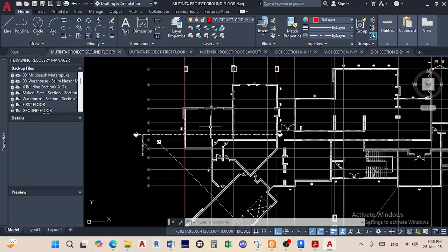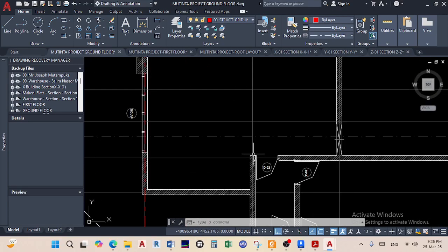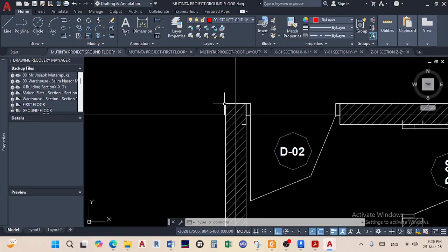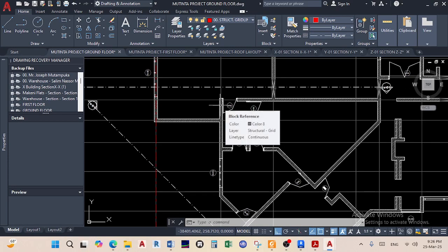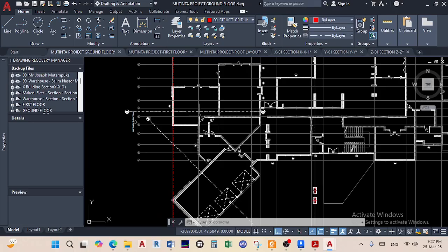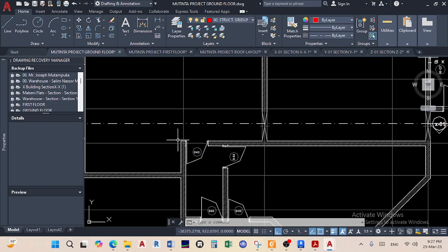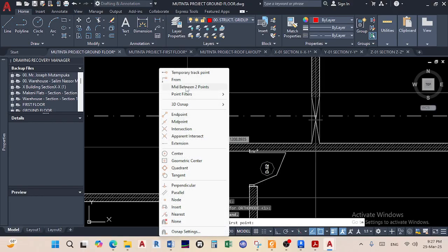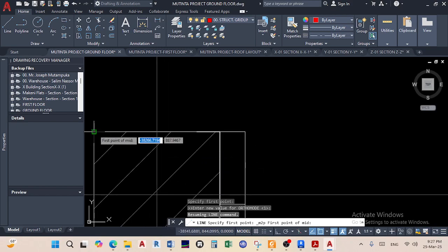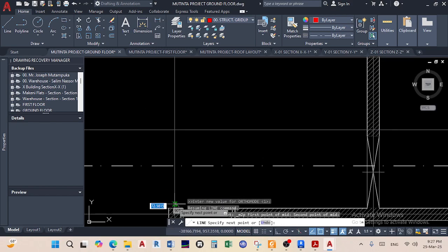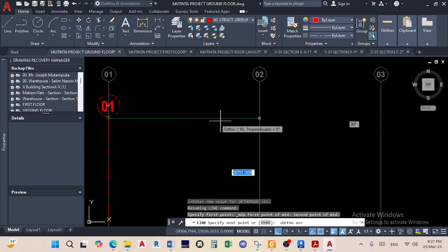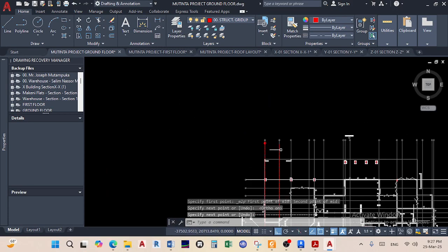So if I do not want to cause a lot of confusion, because these dimensions, like for example last time they were extra by 1. Like if I measure 5,000, it was giving me 5,001. So if that's what I'm trying to avoid, I can go step by step by just using the line tool. Hold down shift, move between 2 points, and then from there to there, my auto will be on, and then I can make sure that they're in the same line like that.